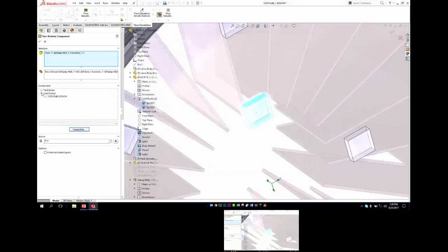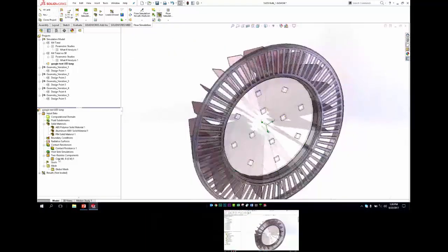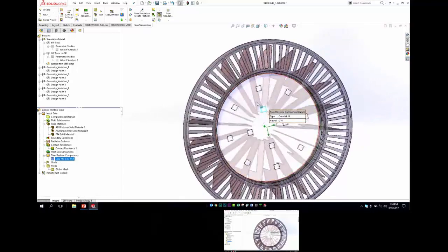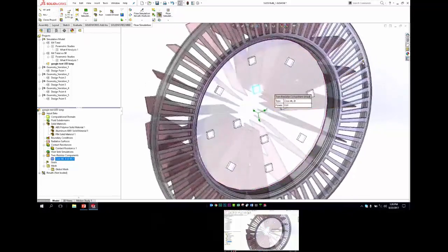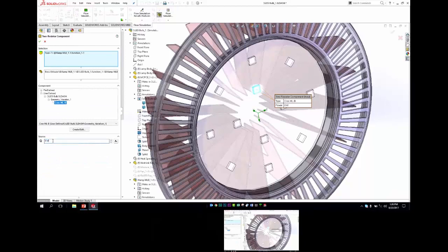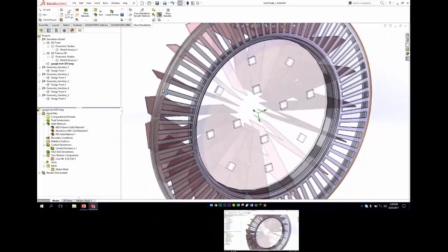and now here we can just apply this microchip value to our part, and we'll end up doing that 11 more times. I already have one of these examples done, so we're not going to do this 11 more times right now. But you can see how simple it is to define a chip. One thing I forgot to do is give it a wattage. So we're going to say that this runs at 0.5 watts. And that's it. That's all the information that I have to add to get the thermal behavior of a microchip, or in this case, an LED chip.